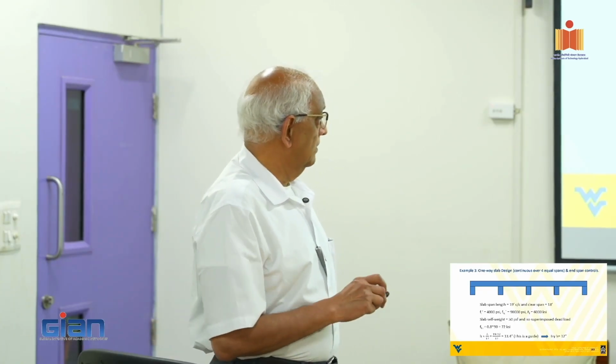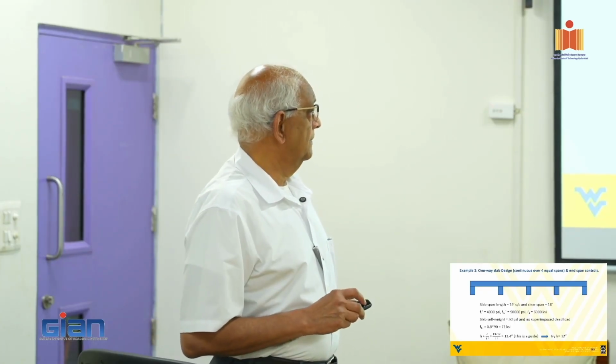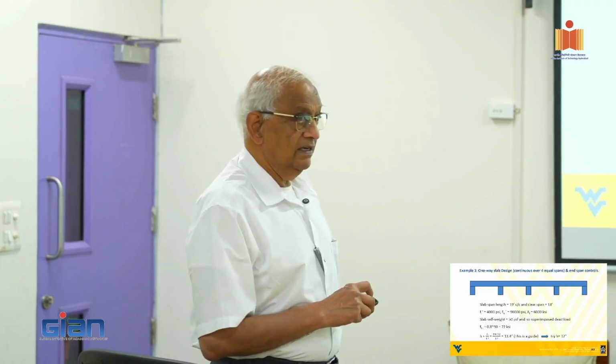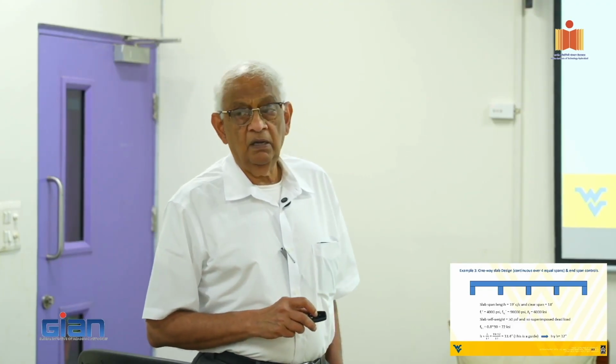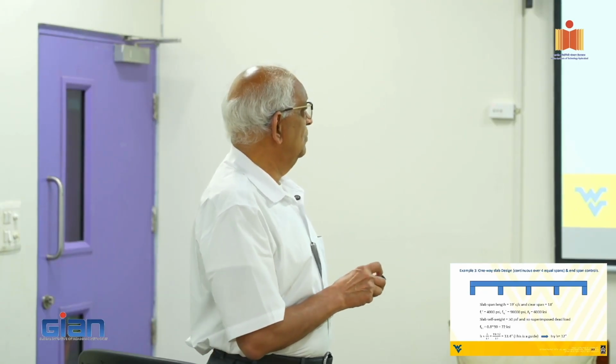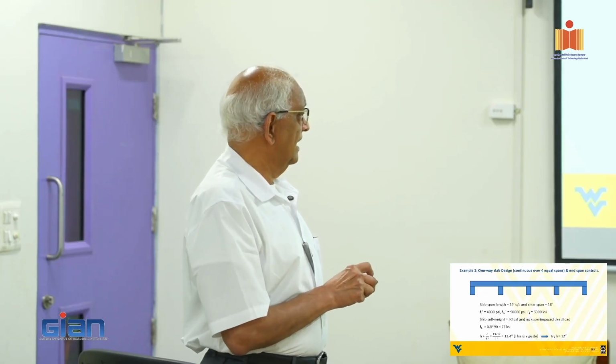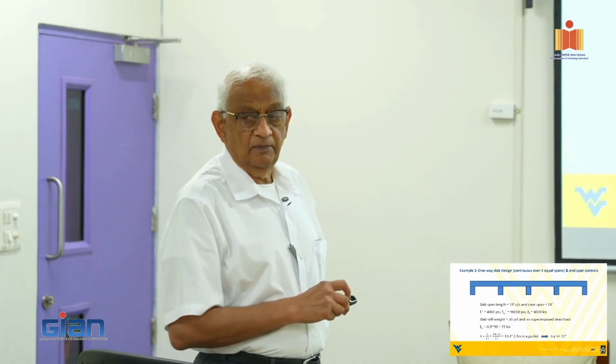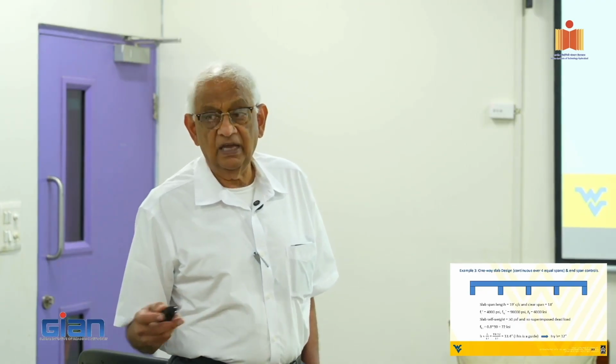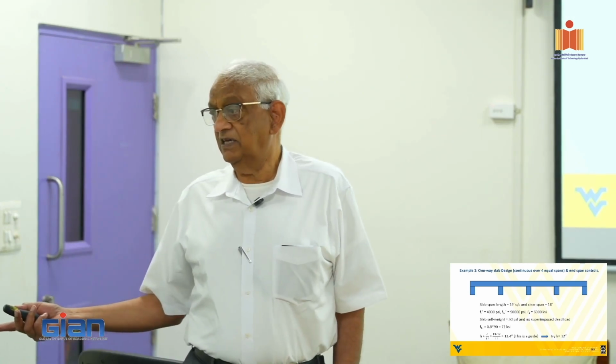As long as it works within a few percentage points, it doesn't matter. All right, so where do we start? As I indicated, for a beam we are talking about L over 12 or something. For a slab, this is where we start. I'm not saying that works. We're going to start with that and cross-check whether it is working or not.